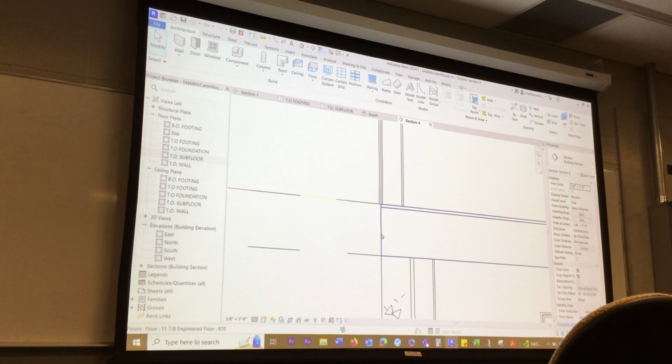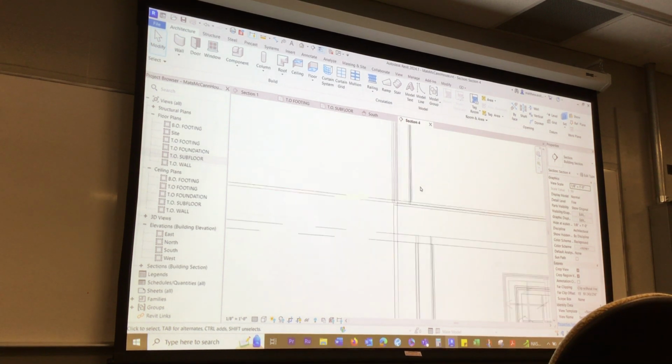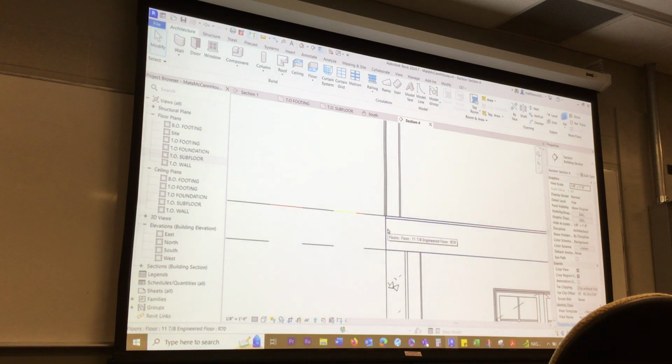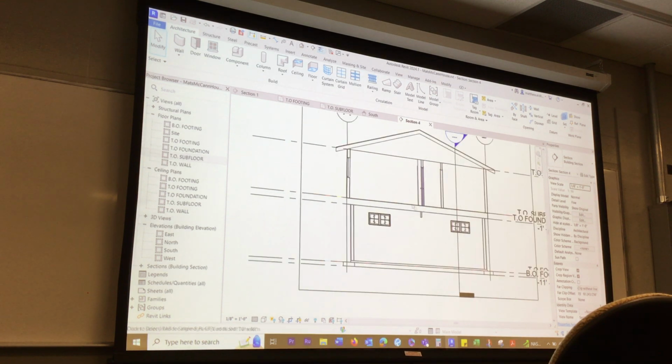So you've got this floor system and you're building the wall in from it, it's overhanging the foundation. And the foundation, same thing, to the grid line. That's why we put the grid lines there. So the grid lines have to mimic the DWG, and then the house has to mimic that. I know you guys know this stuff, but a lot of it is just zooming in and identifying the correct line. So sections are the way to check, right? So if I zoom in here and I see this is moved, or maybe I've moved the wall or whatever, then I can start running around trying to diagnose it, okay?